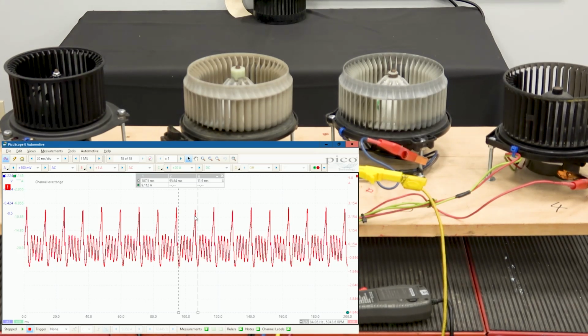So the point I'm making with this pattern is, here's a blower motor. Maybe I've just replaced the blower motor resistor and the customer takes the vehicle. This is the kind of vehicle that's going to turn up back in my shop in 2-3 months down the road with a failed blower motor, and possibly, depending on how it fails, a burned blower motor resistor or resistor pigtail or connector. So that's using a current probe to get insights into problems with different types of blower motors.